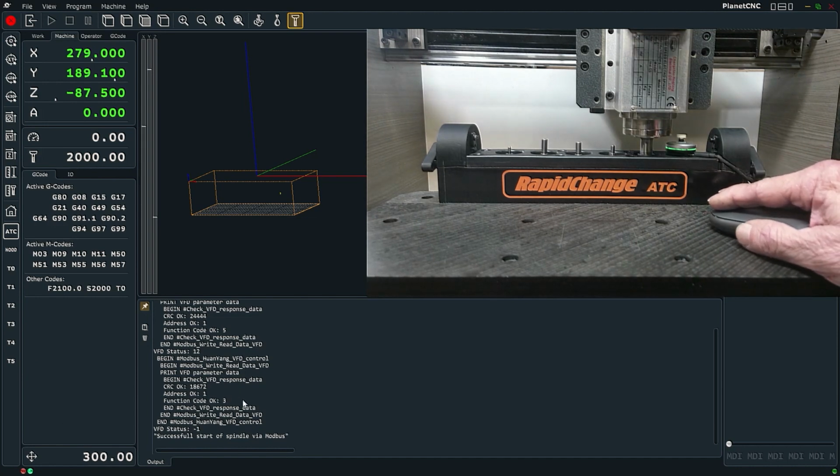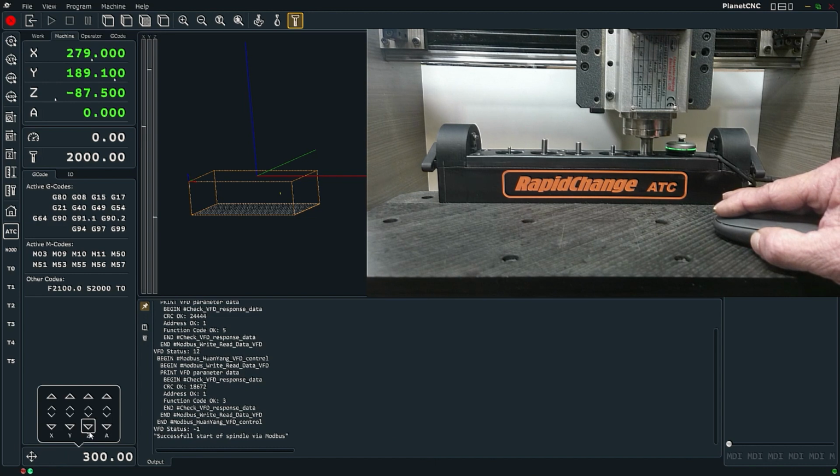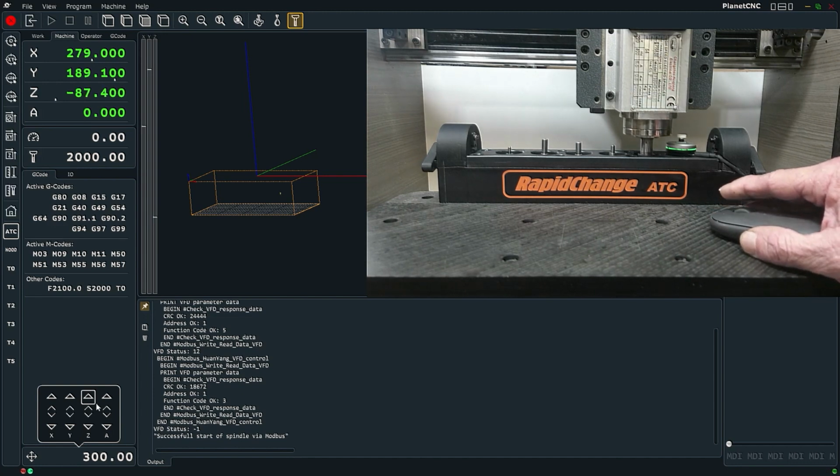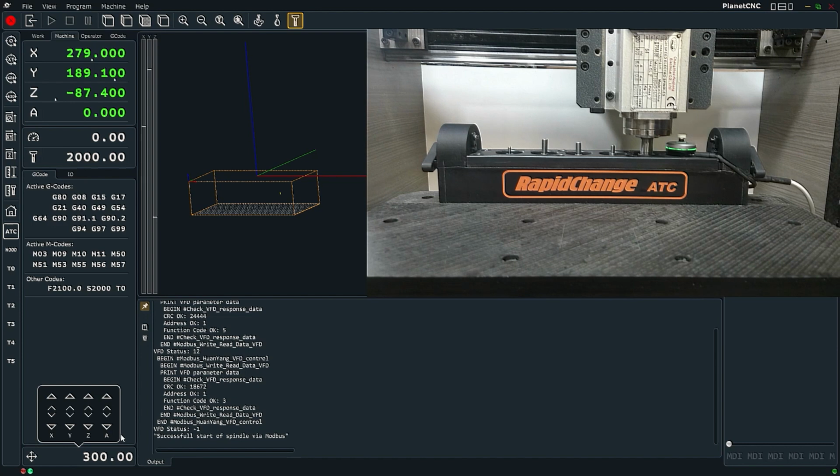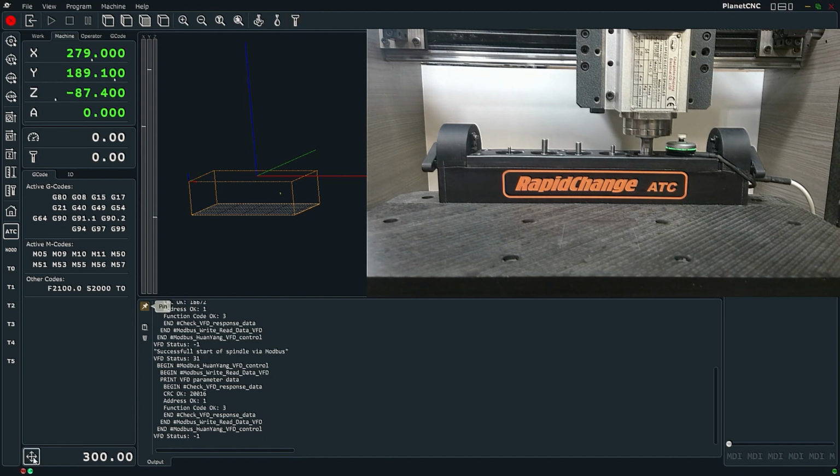Okay? When you make connection, engage, you want a solid smack. So if you hear any kind of noise like that, any chattering like that, you're not engaging fully with the socket. So basically right now, we're just making sure that we're not rubbing on the sides of the pocket, and we're centered up. And turn the spindle off here. And now we're going to bring Z down.